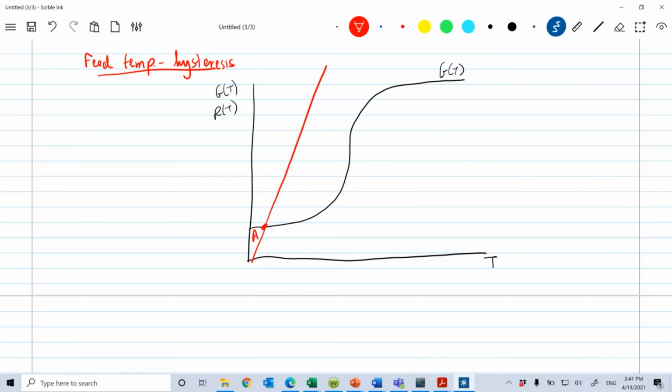So you're starting up the reactor, there's no conversion. You heat up your feed a little bit, and you get to a second point where there's a little bit of conversion, but it's not much. Then you heat it up a little bit more, and you get to this curve. Now your reactor is operating at point C, although it's touching here as well, because you're not producing a lot of heat, so you're still at point C. But you know from your curve that there is a tangential point right there. That's just something to keep in mind.